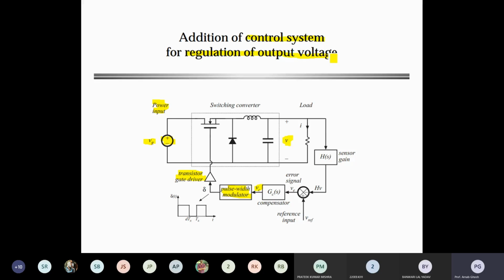For this reason many manufacturers specify an input voltage range for which the power supply output will stay within the specified limits. I have already told you, the rating of the power supply is most important, and how much variation you can allow for it. That means the tolerable range is also a very important issue. So I think all of you are able to understand line regulation.